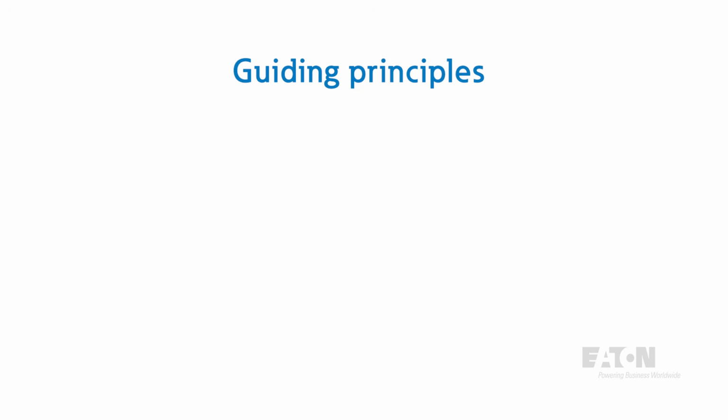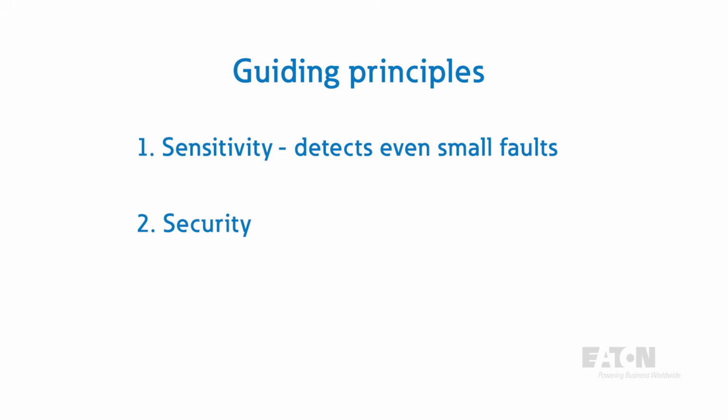At the core of this approach are two guiding principles: sensitivity and security. Sensitivity ensures we detect faults quickly, even when they are small. Meanwhile, security helps us avoid unnecessary trips so we don't disrupt areas that aren't affected.